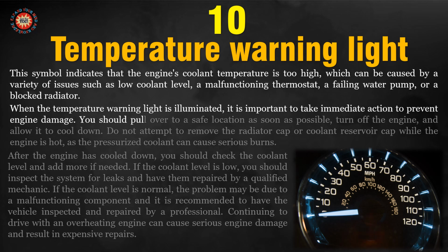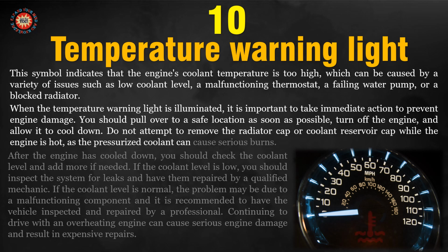You should pull over to a safe location as soon as possible, turn off the engine, and allow it to cool down. Do not attempt to remove the radiator cap or coolant reservoir cap while the engine is hot, as the pressurized coolant can cause serious burns.